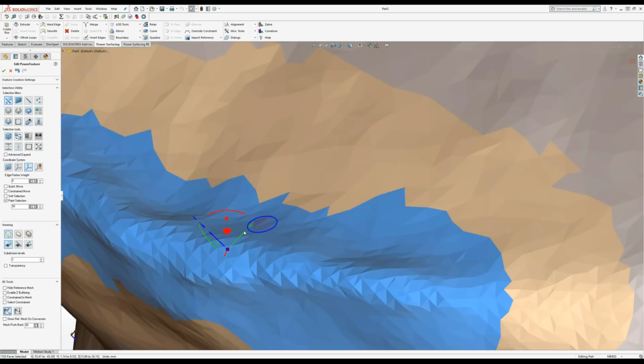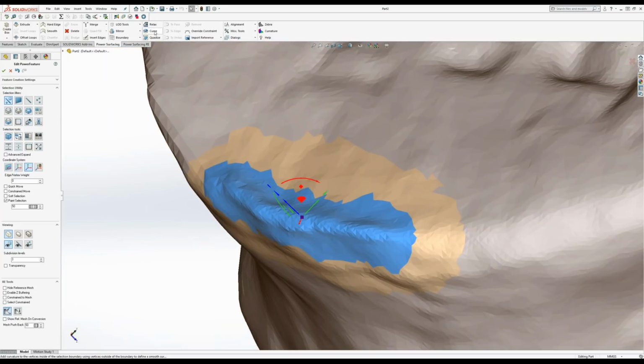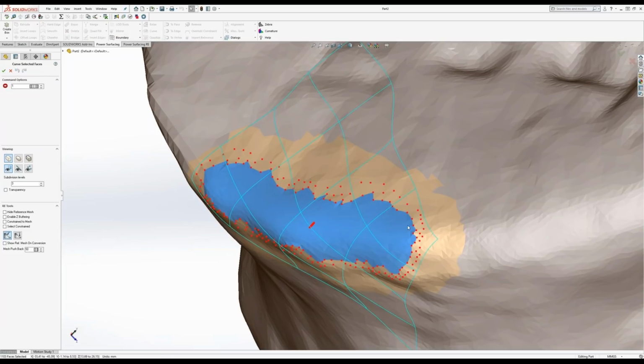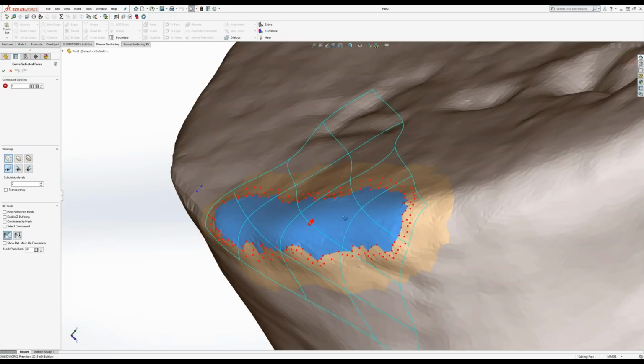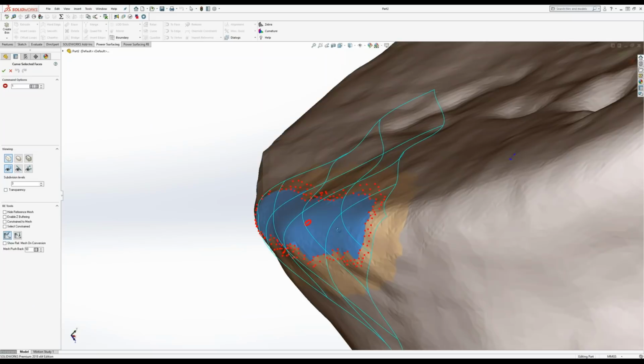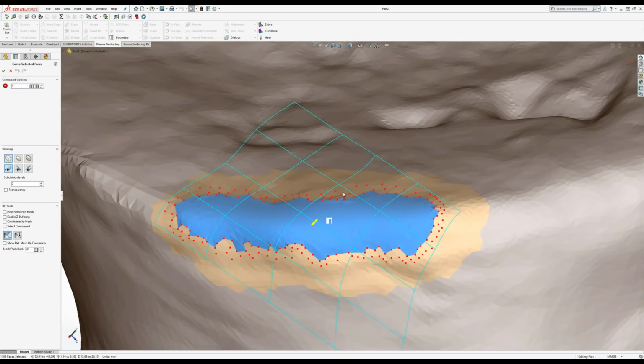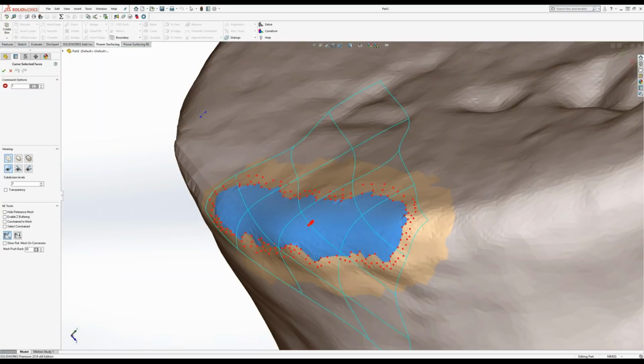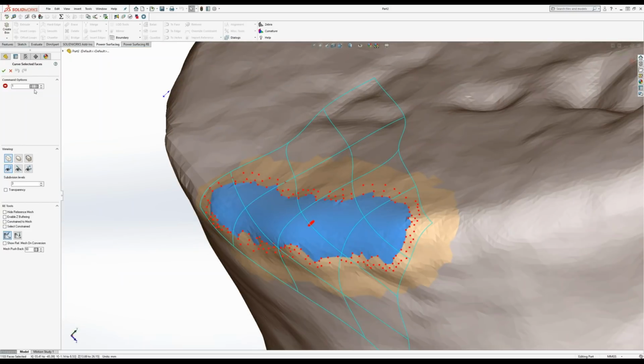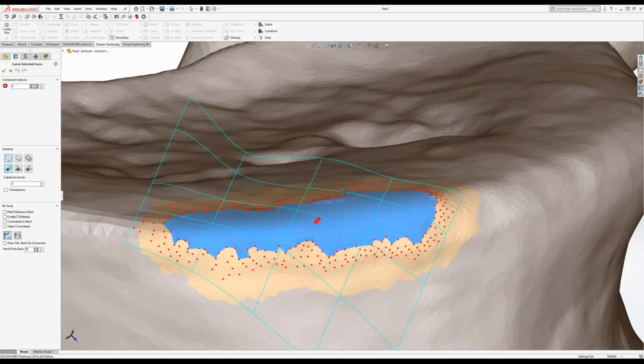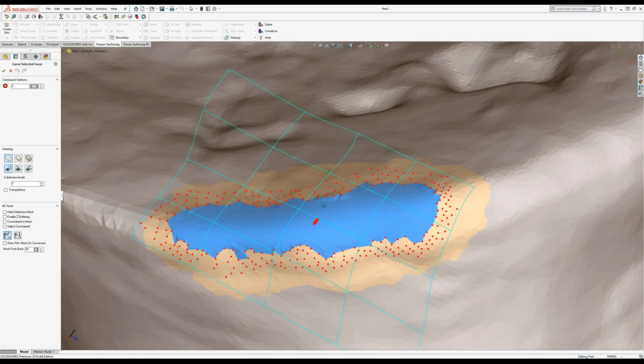And I'm going to use another tool. This tool is the curve. And what it will do is it will fit a surface over a ring of vertices around the outer edge. And then it will fit all of the interior vertices to that surface. So you can see the surface displayed in cyan here. So that's another way to solve a similar problem. And you can change the number of levels that you go out on the other mesh to get a better or worse curvature on it. You can see we've done it there. So that's one way to do it.